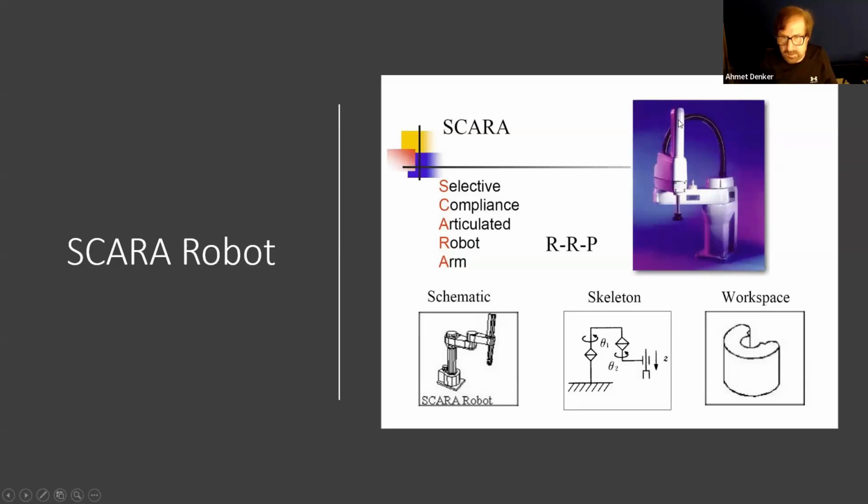So here it's parallel. So sine term becomes 0 and cosine term becomes 1. So this way, the nonlinearity is avoided. That's why this type of design is given a special name, SCARA type of robot, and this is quite popular because it is easier to control.